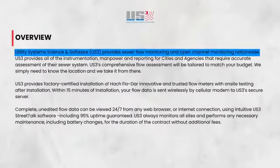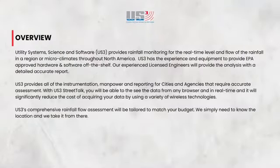But then we back it up with data. So we put a flow meter in where we think we're having a problem. And so we need two different types of data. We need dry data, and we need wet data. We need wet data being that rain data. We also try to quantify that rain data. We'll have rain gauges, and there's a lot of free data available through NOAA. So we don't necessarily need to put rain gauges in unless it's not being covered by some free data.